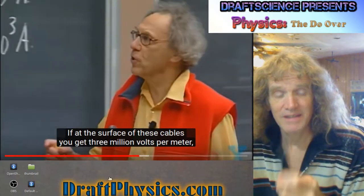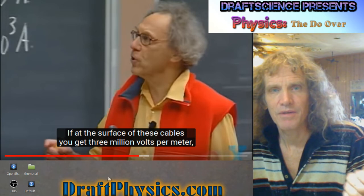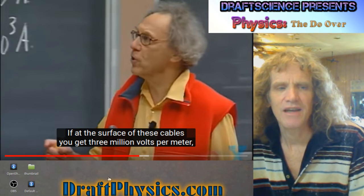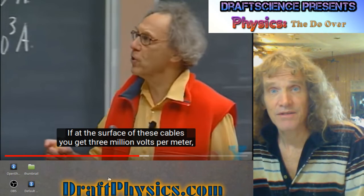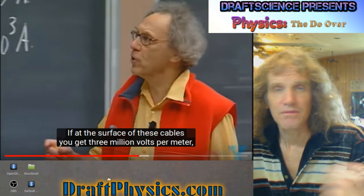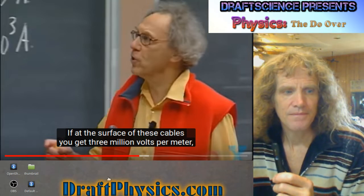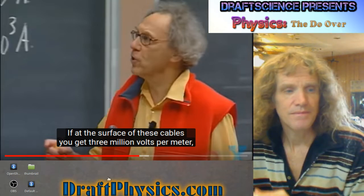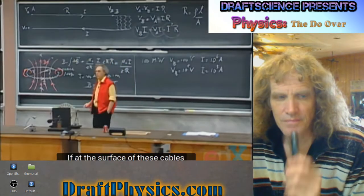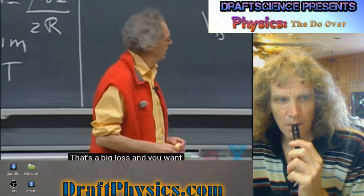Obviously, the 3 million volts doesn't really have anything to do with reality. We already know that you can't go much over 300,000 volts without having substantial breakdown. So you have to keep it somewhere lower than that. Atmospheric breakdown of these cables, at 3 million volts per meter, you get corona discharge. That's a big loss, so you want to stay away from that.